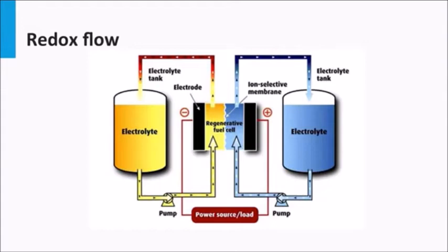Redox flow batteries are a very new technology which seem to combine the properties of both the batteries and the fuel cell. The different reactants only exchange ions in the form of electrolytes through a membrane in a cell. Thus, the cell reactions proceed without a physical mixing of the reactants. The chemical energy in a redox flow battery is stored in its two electrolytes, which can be maintained physically separate from each other. Redox flow batteries thus have a high life expectancy.